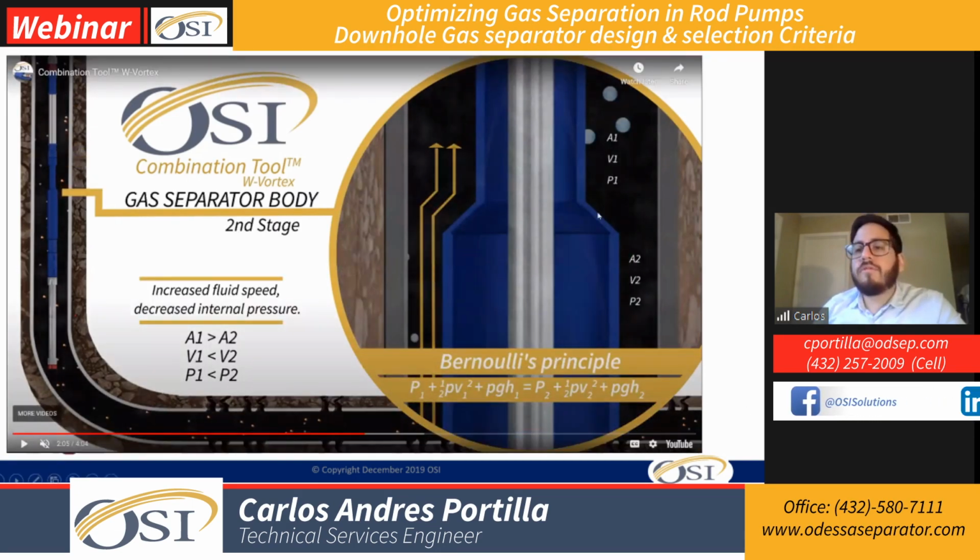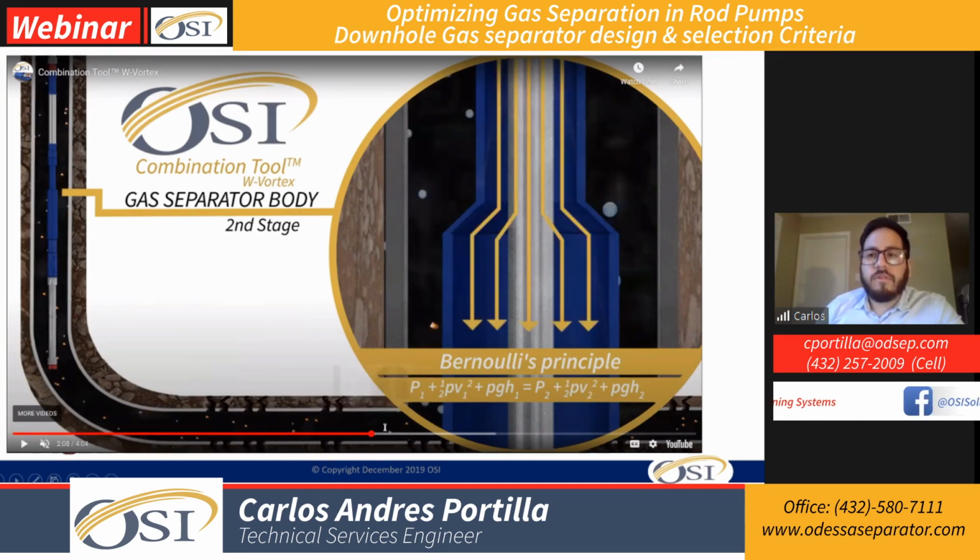In the gas body, we'll have two sections. On the outside, what we have is a reduction of area. What is happening here is we have a higher velocity, so we'll be applying more energy to those gas bubbles for them to keep rising. We also have a lower pressure zone, so we can separate gas here, and then we have more free gas at the top. When the fluid is already inside, it's the opposite.